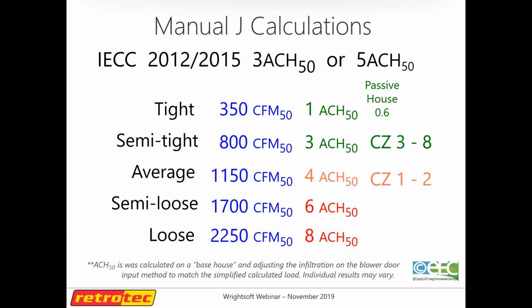because the way it works is you end up having to split the difference. It'll be like, well, it's 1.5 air changes per hour for cooling, but it's 2 air changes per hour for heating or something like that. The math is so dissimilar that they don't match up particularly well. And it depends on climate. Yes, of course it does. So you're going to be closer to tight in, say, a southern climate than in a loose climate. Your tight is over 1 air change per hour in heating, for example. So it's not a perfect lineup like that.